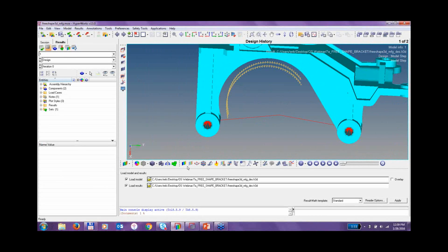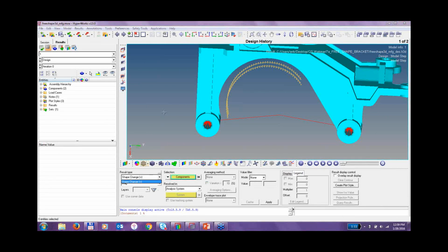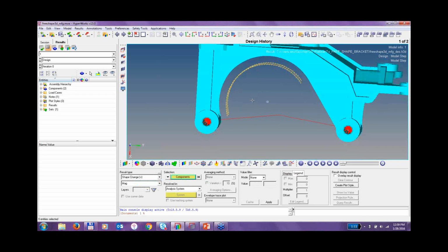And I can't do it. There is a high stress that's occurring in this region here. So we know that there has to be a cutout for this compressor. And we know that we could probably tweak the shape of this curve here that would optimize the part so that we would get rid of the localized high stress.